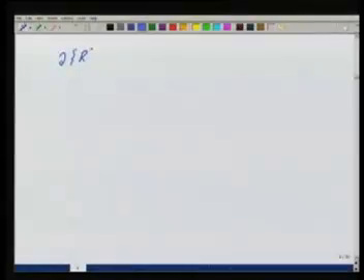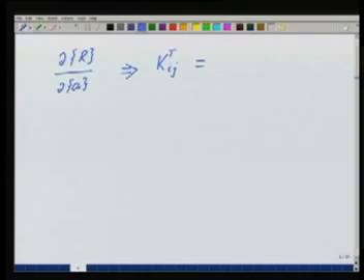Now how do we write this del R del A? This will be equivalent to saying that I want to find some matrix which I will call, you will see the reason, K_T_ij, the entry of it is equal to del R_i del A_j, evaluated, because let me now change my naming system so that we don't have a problem here.